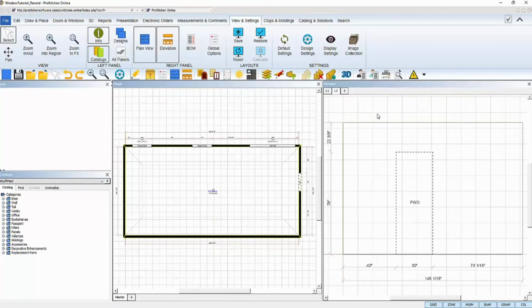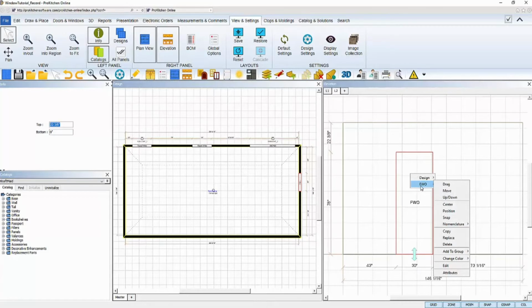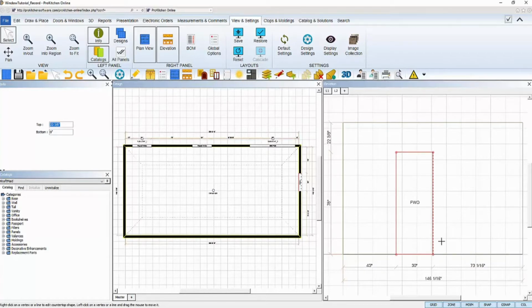Open the wall opening in Elevation View, select it, it will outline in red once selected, and then right-click and choose the Edit tool from its toolbox. Once in edit mode, the corners will turn into radius points, and you can now click on a line or a point to edit and move it.